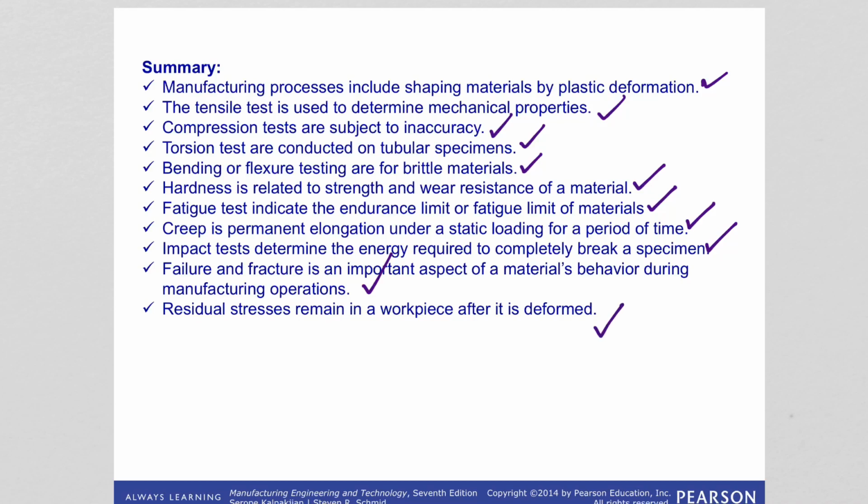If we work on the material and cut some parts of it, there will be an inhomogeneous distribution of the stresses, and when we cut it, the material is going to bend in certain regions.